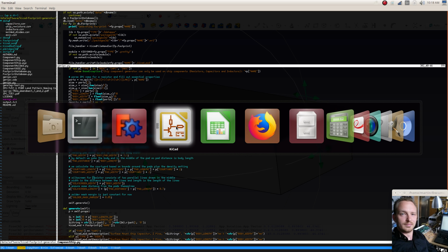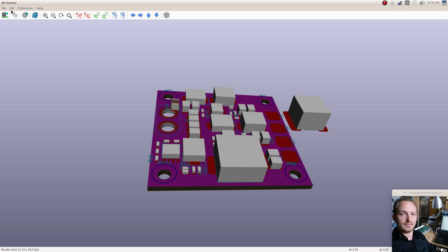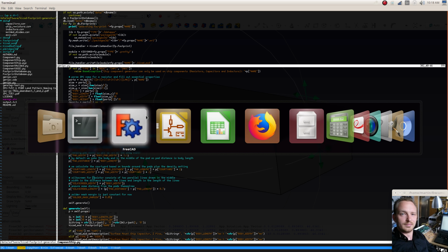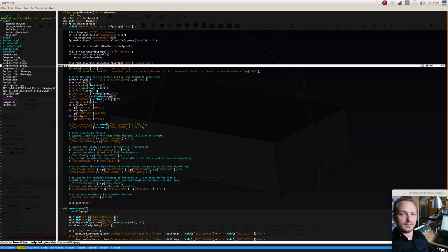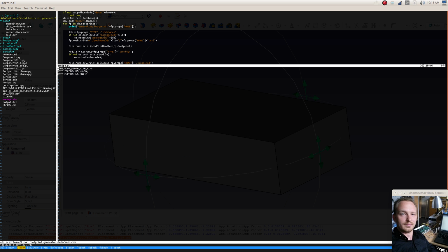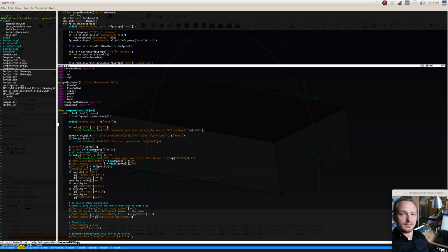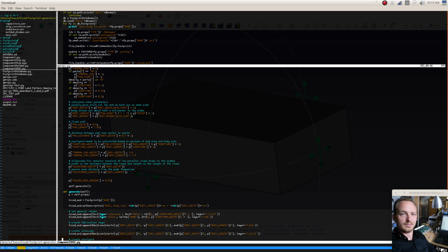So just from the width and length of the package, this script generates a default footprint. And we can compare it to the default KiCad footprints, and we can see that it's basically the same. And I'm doing the same for the surface mounted IC packages right here, where I generate a surface mounted IC with width of 6 millimeters across the chip with pins, and height of 1.75, and it has 8 pins, and it's normal board density. So let's go. Is there anything interesting about this?